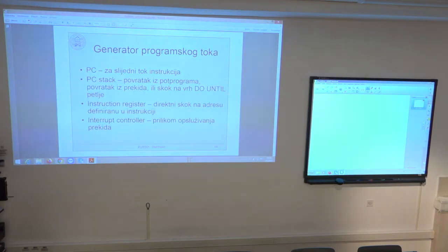Because if you have a conventional CPU, you have some register where you have the loop counter value. And then you take this register, decrement by 1, check if it is come to 0. If not, then you jump to the top of the loop and repeat the loop until the counter is expired. All of this is done automatically in hardware. Why? Because